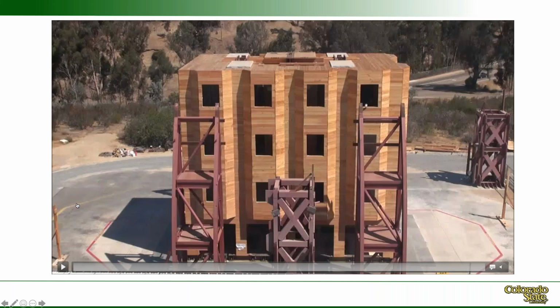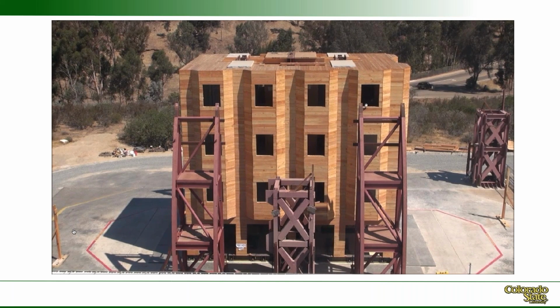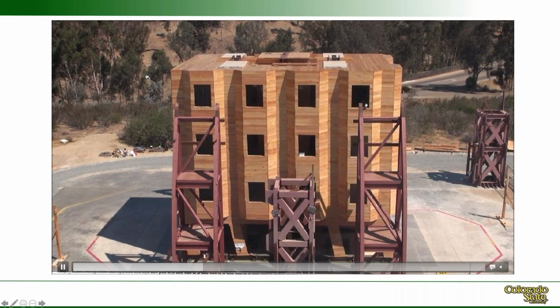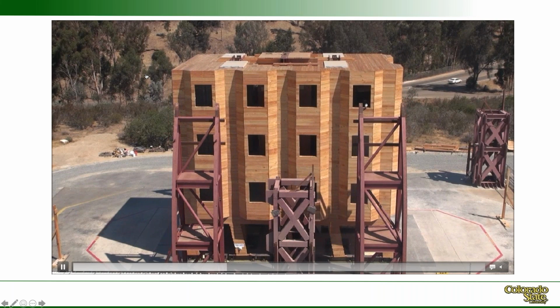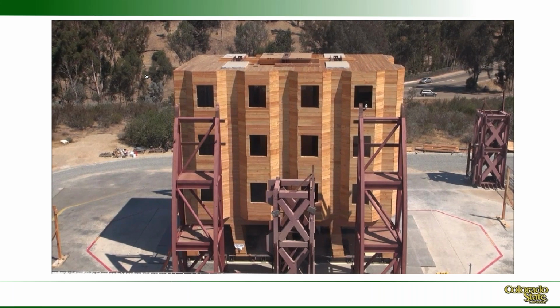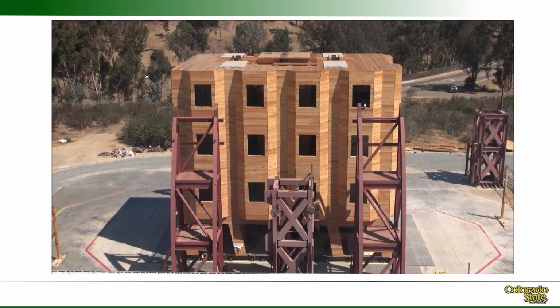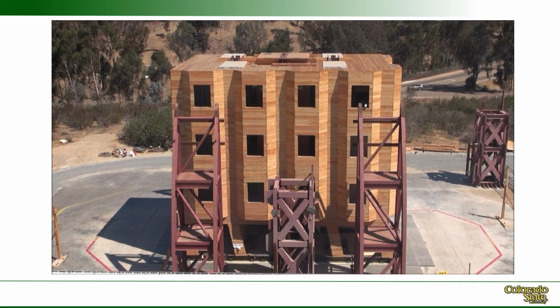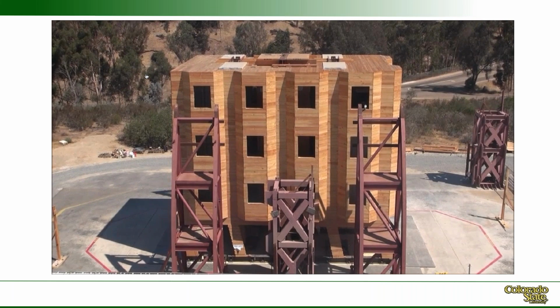So this is the shake. We've muted the sound just to avoid feedback for you, but I'll try to narrate a little as we go. This is the full-scale 4-story building. This is a 1.8 g spectral acceleration Superstition Hills shake. There's quite a bit of seismic mass added to get us up to design weight or design mass, so there are steel plates and other things throughout the building, distributed as evenly as possible. You can see we're not quite collapsing, but this building would have to be demolished because the bottom is at close to 17% drift at the base there on that first soft story.